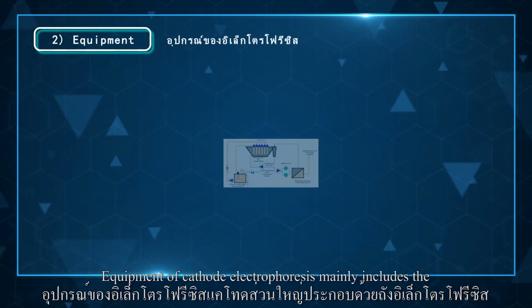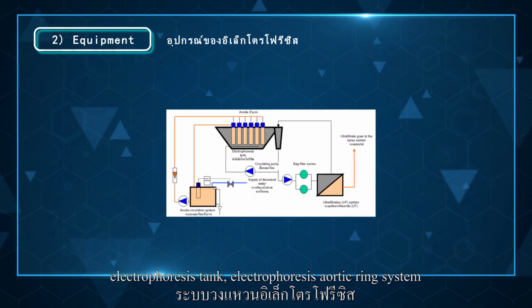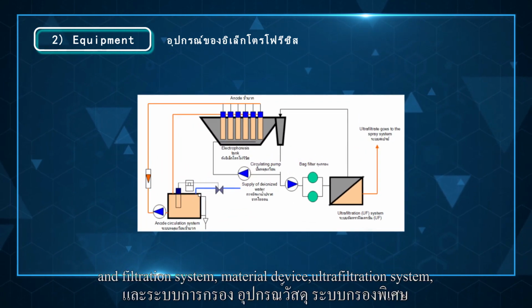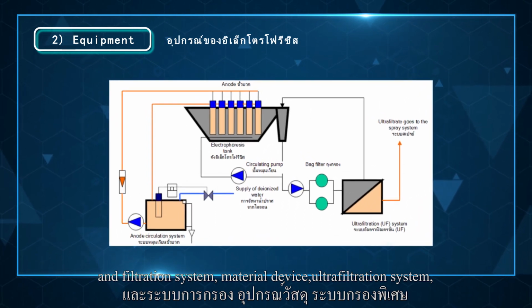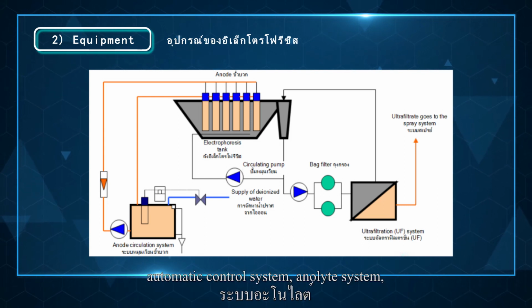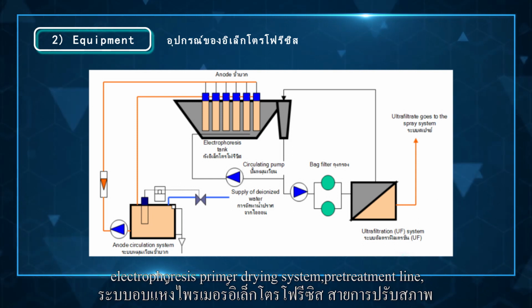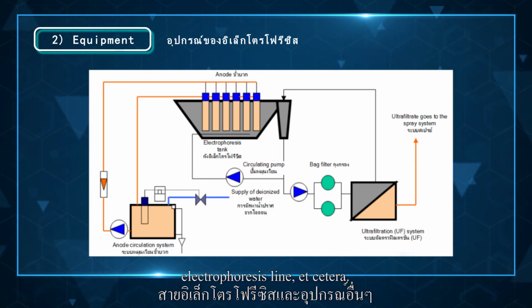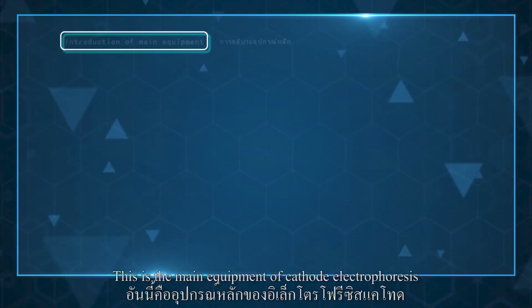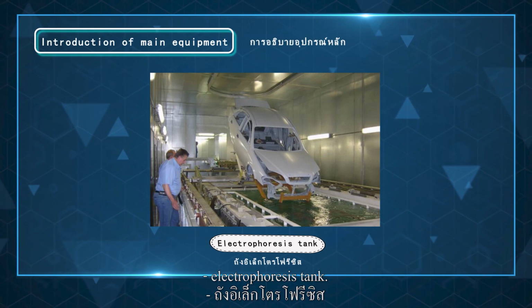Equipment of cathode electrophoresis mainly includes the electrophoresis tank, electrophoresis circulation system, filtration system, material device, ultrafiltration system, electrophoresis tank liquid temperature automatic control system, analysis system, DC power supply, post-electrophoresis washing system, electrophoresis primer drying system, pretreatment line, electrophoresis line, etc. This is the main equipment of the cathode electrophoresis tank.